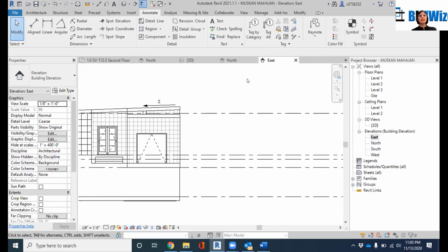That taught me, and just imagine it was one room. What if I had to do the whole house and each room I had done to that detail? I would have literally blasted my computer. And at that point of time, I did not even have a very powerful computer and I still went ahead and detailed everything. So then I realized that not everything needs to be a 3D model in your drawings. You have to pick up things where just drawing a few lines will give me the detail. So for that, we use detail lines.